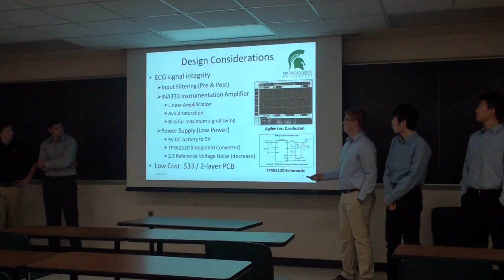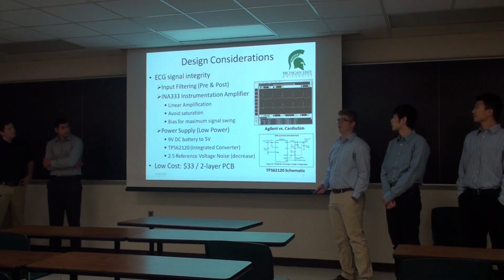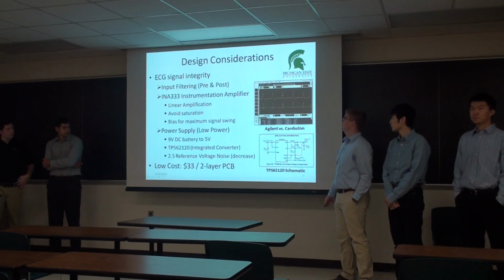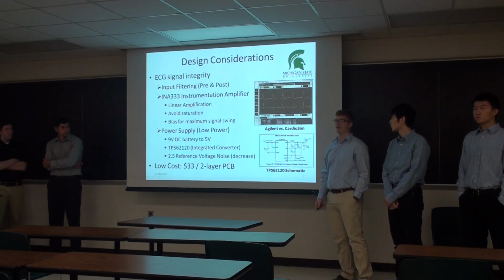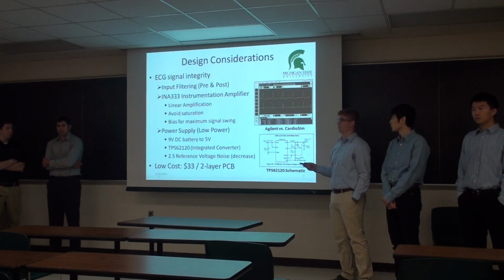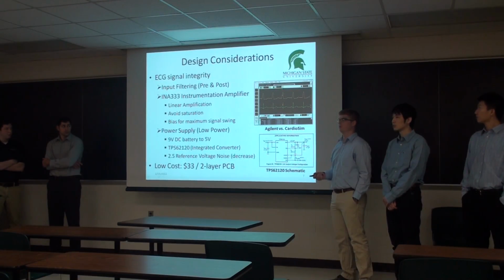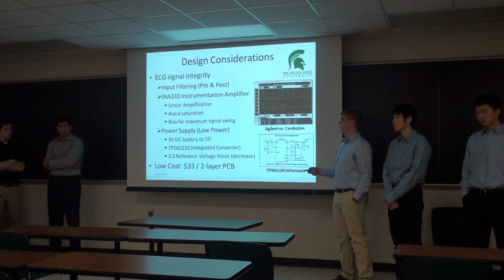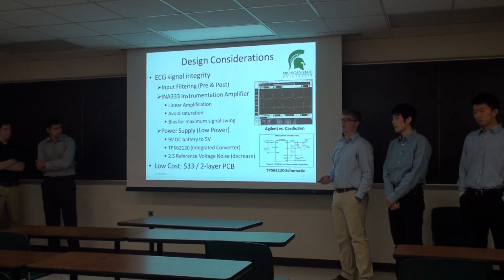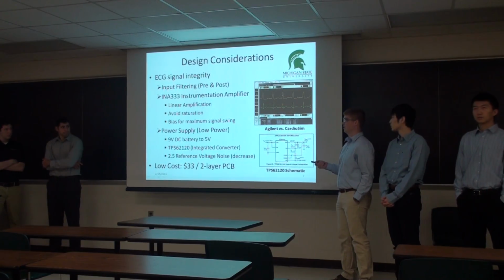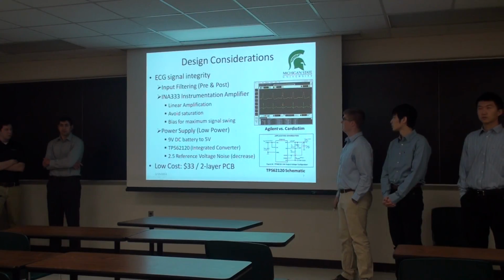So, as Yuan was saying, one of the most important things for our design is that we have a clean reference voltage. We're using a 9-volt battery and a buck converter to buck down to 5 volts to deliver a low power application. One of the challenges with using a 5-volt single supply is that we have to bias all of our signals between our ground and our 5-volt references.